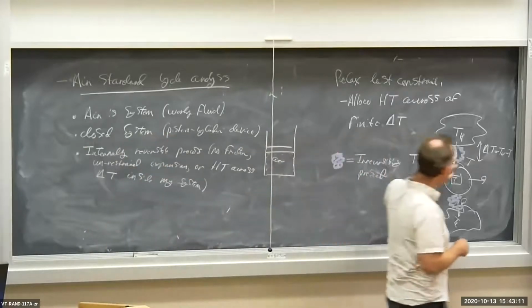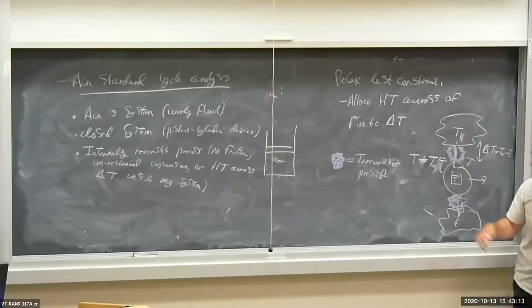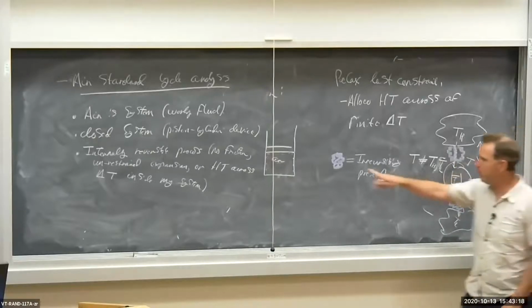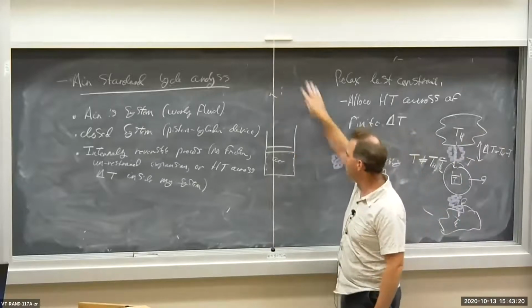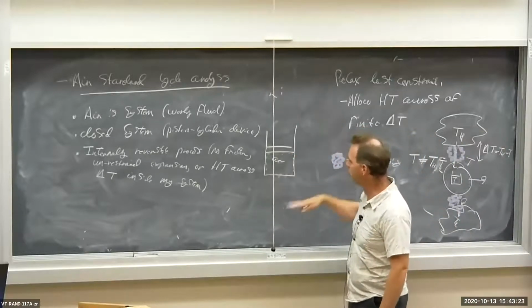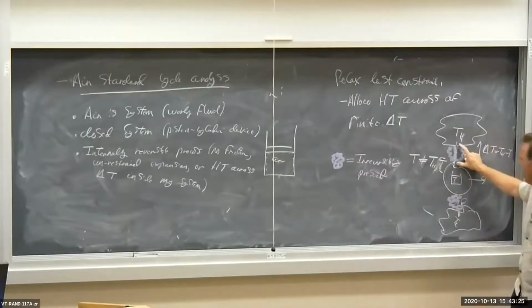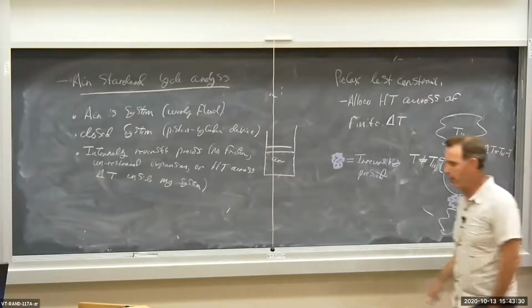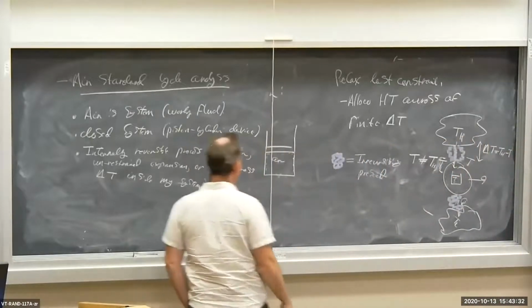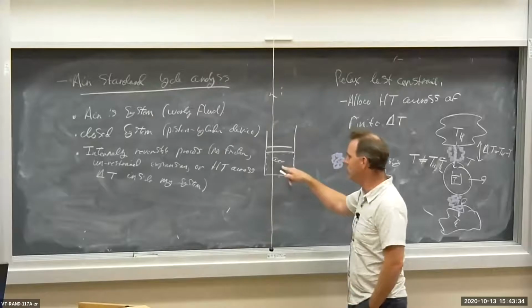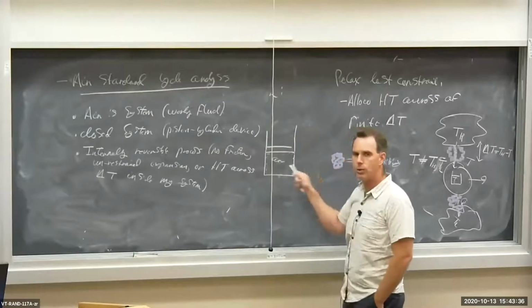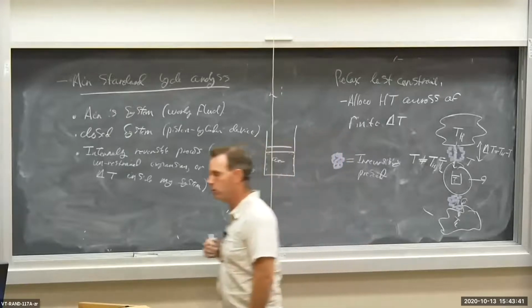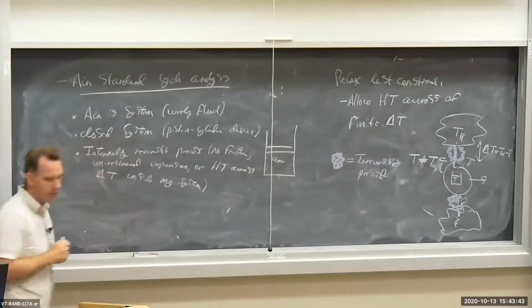We can have heat transfer across a temperature difference outside the system. In other words, between the piston cylinder device and wherever it receives or rejects heat from or to. We can definitely have a delta T between the reservoirs and the system temperature when we have heat transfer, but there can't be any temperature variations inside the system resulting in any heat transfer, okay? Temperature is always spatially uniform inside of my system.